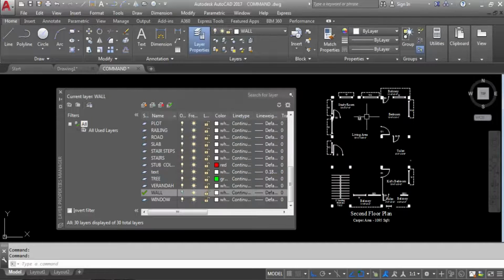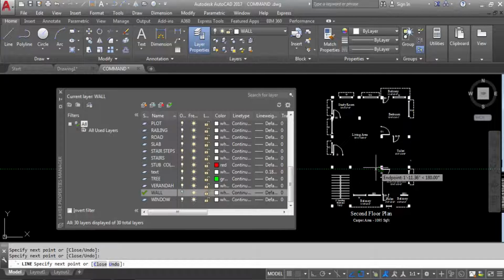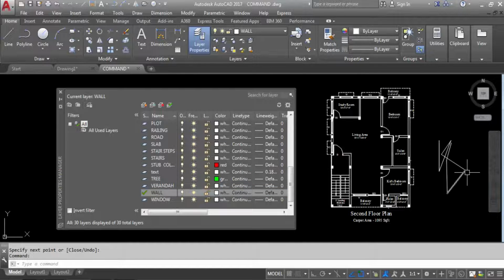Next we will discuss layer lock. So hope you understand those points. Objects can be created in a turned-off layer. The turned-off layer can be set current. The objects of a turned-off layer cannot be modified, and the objects of a turned-off layer cannot be seen.